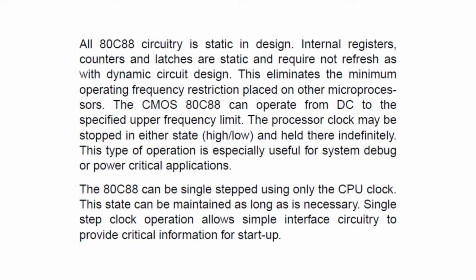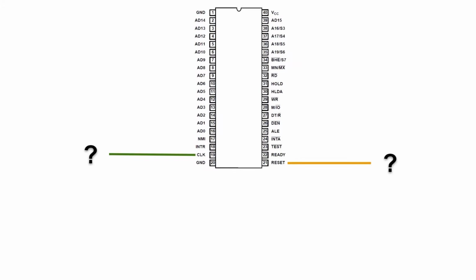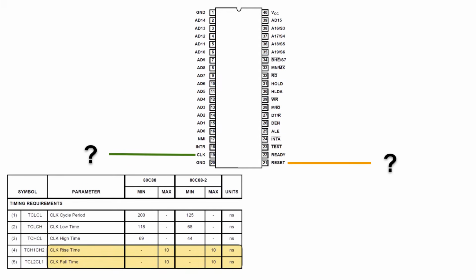Unfortunately, we can't simply hook up a tactile button to the clock input and expect it to work, and there are two reasons for that. One is the fact that the button would generate multiple impulses every single press due to the vibrations of the pins. We could use a low-pass filter with a resistor and capacitor to filter those vibrations out, but this would cause the signal level to change slowly, and not be digital really, while the CPU has a strong requirement for the clock signal to have the rising and falling edges very short, shorter than 10 nanoseconds in fact.